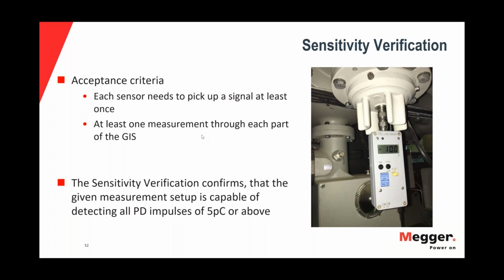So basically the sensitivity verification confirms that the given measurement setup is capable of detecting PD pulses of 5 picocoulomb and above. This is the purpose of the sensitivity check.